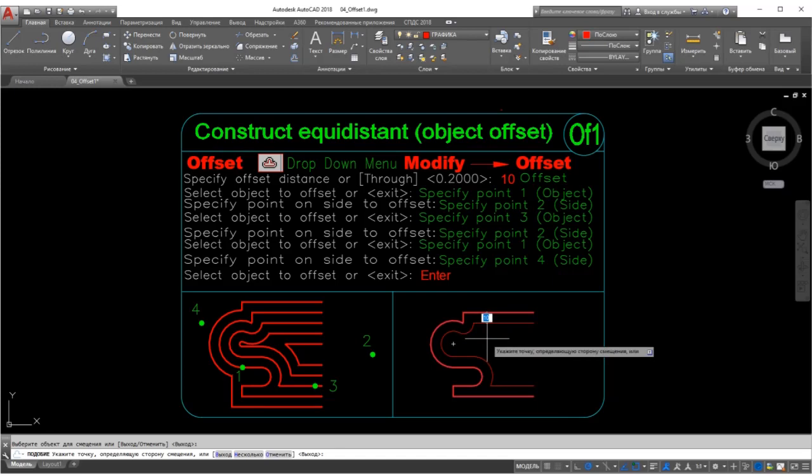Select object to offset or... Third step, select a single object such as a line, a polyline, or an arc. Note that you can select only one object at a time with the Offset command. AutoCAD asks where you want the offset object. Specify point on side to offset or...